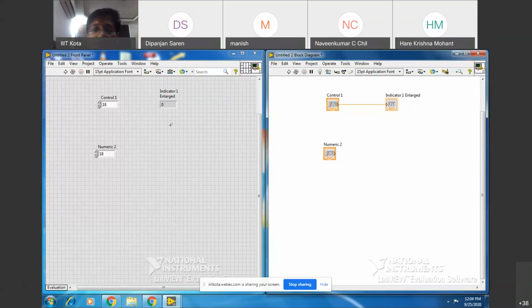So now what I have done is connect the control 1 output to this. Now, could you see on the front panel and the block diagram, in the top row, number 2, there is one arrow button, that white colored arrow button on the left side? That is for run. If this arrow is continuous, your program looks fine. And if there is some error, this arrow will be broken and gray colored. It will not be white.